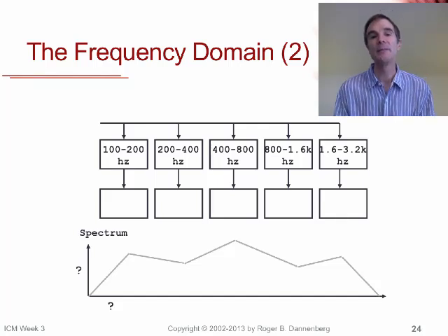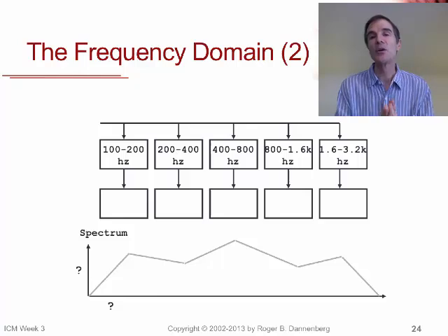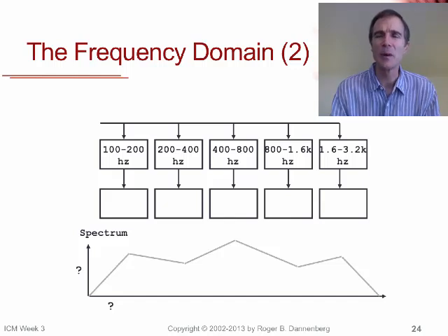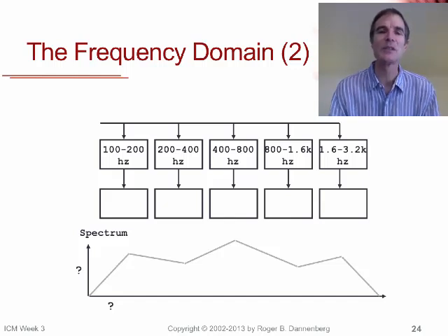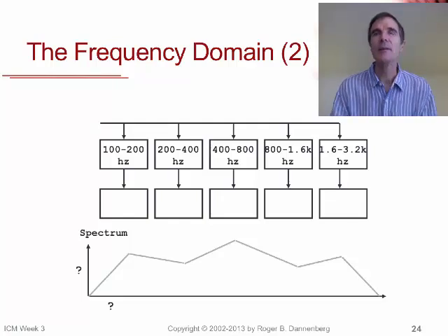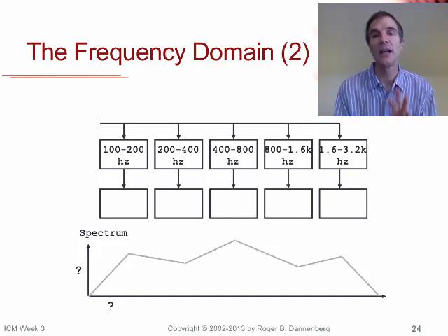How do we do that? Well, of course, I showed you the math, so we're forming these integrals. But why integrals, and why are we multiplying by cosines and sines? And what's going on here? Essentially, what happens is when you multiply by a cosine or sine and take the integral, you're constructing a filter.